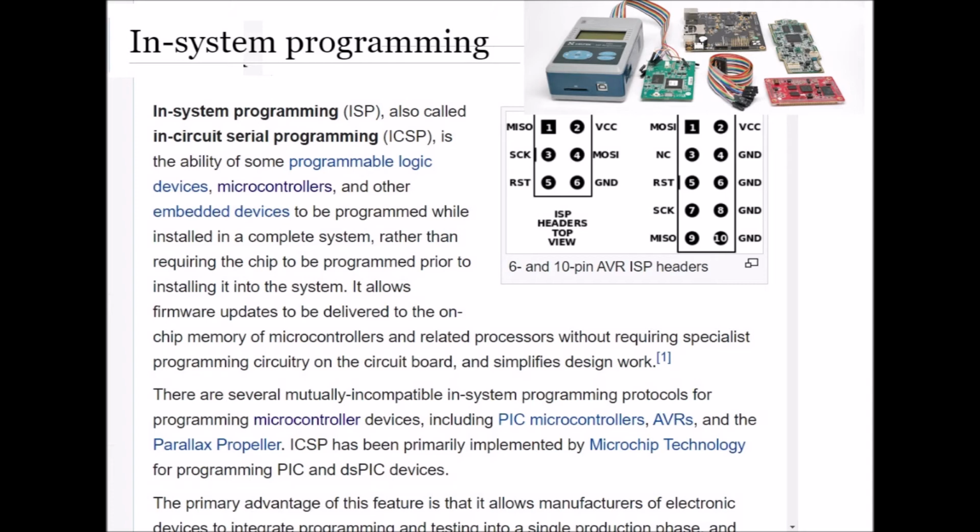In order to facilitate easier integration with automated testing procedures, other devices usually use proprietary protocols or protocols defined by older standards. In systems complex enough to require moderately large glue logic, designers may implement a JTAG controlled programming subsystem for JTAG devices such as flash memory and microcontrollers, allowing the entire programming and test procedure to be accomplished under the control of a single protocol.